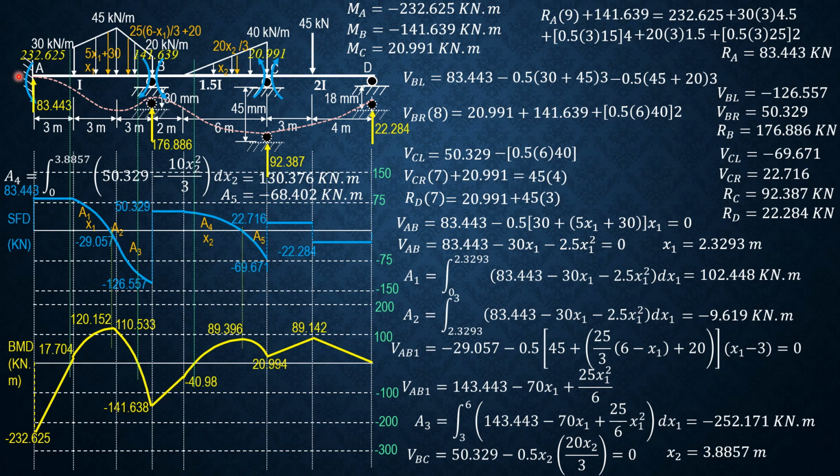Then we now sketch the elastic curve. So 0 tangent there, positive in this portion, negative, then concave up for this part because it is positive moment in this range. So that's it for this problem, and this is really the last example on 3 moment equations. We will solve this, verify the moments by slope deflections and by moment distribution method in the future.